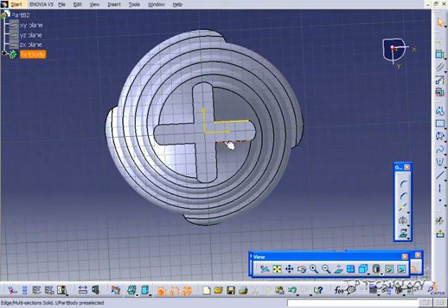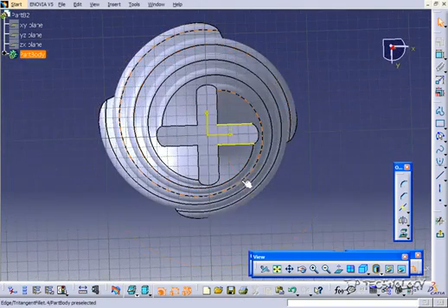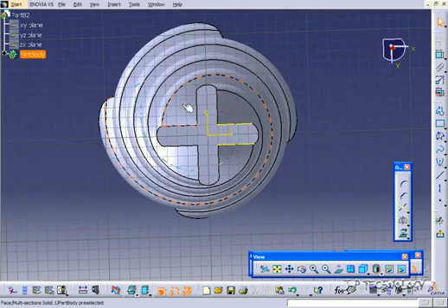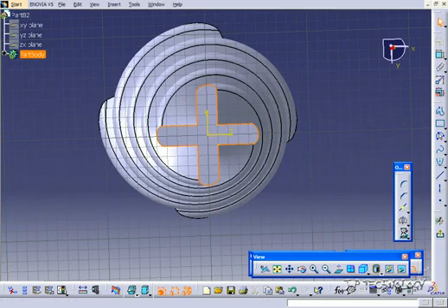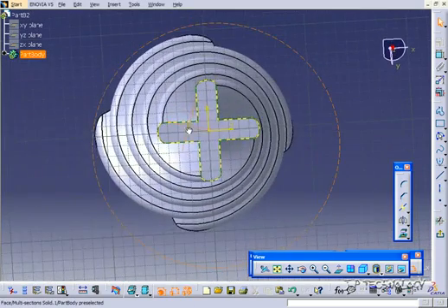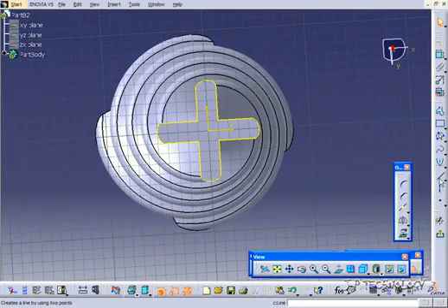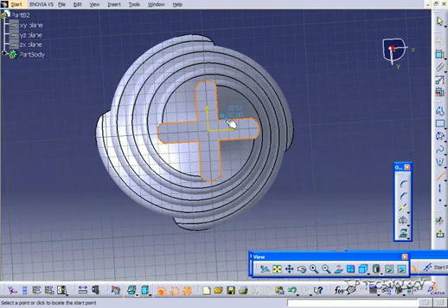Now it can also work the other way. You can click a line, and you can click Project, and it'll be projected. You're also able to click on, say, a whole face. So let's click this face, click Project, and we projected all the lines touching that face. Now, if we go again with our line tool, we're able to snap onto all of these points.